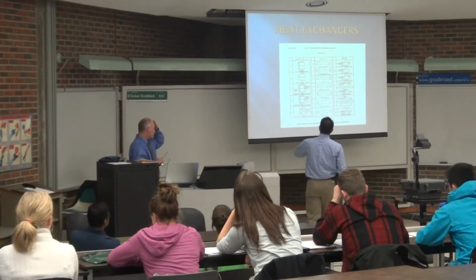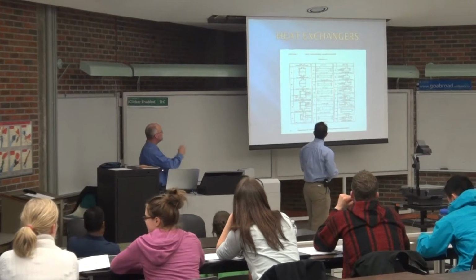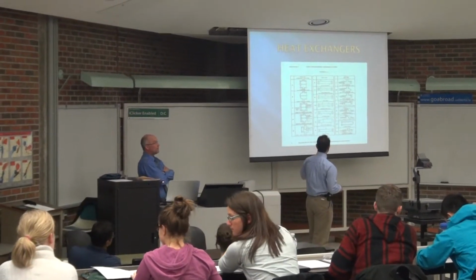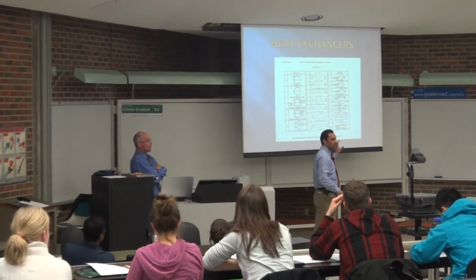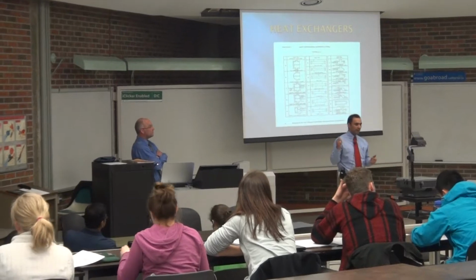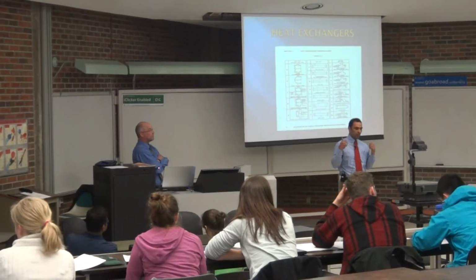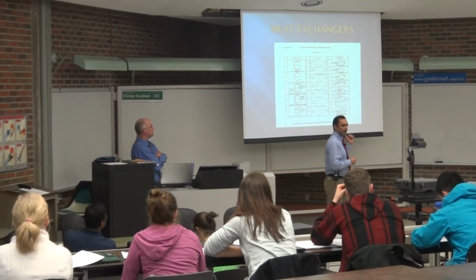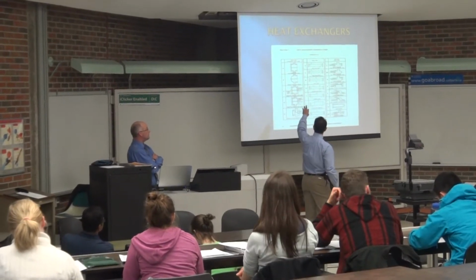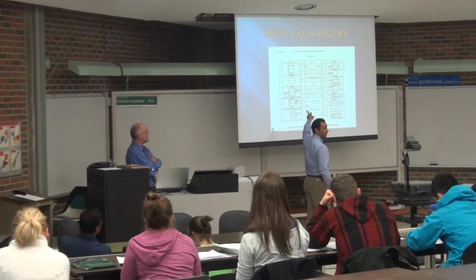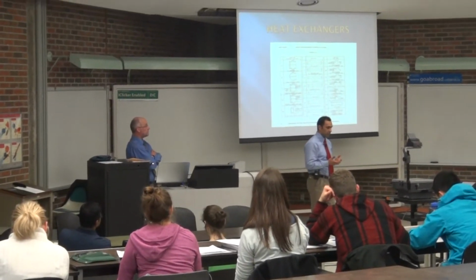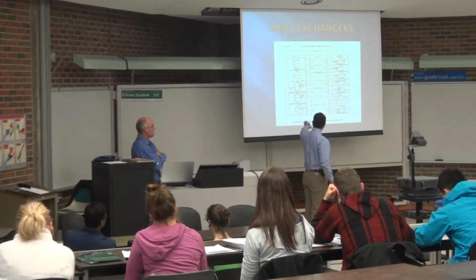So if you look, the first column, these are the front heads. It shows A type, B type, C type, N type, D type. Every head has its own importance. Like A type can be used where you want a quick inspection of the tubes and you want to remove the bundle. And you can replace that with the cheaper B type head because you're not putting an additional flange and cover on there. You're just welding a semi-elliptical head. So if you have a high pressure exchanger, then you would want to use the D type head.